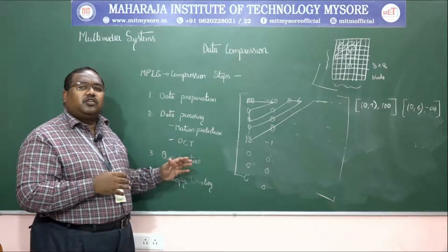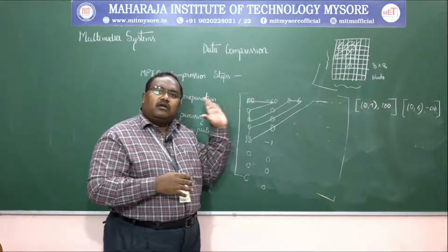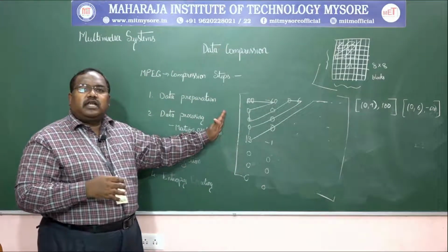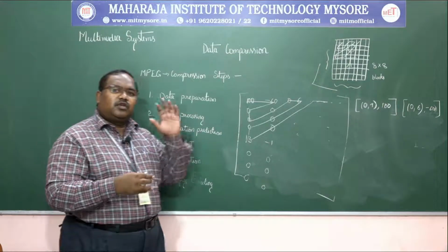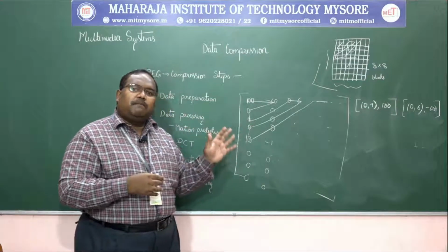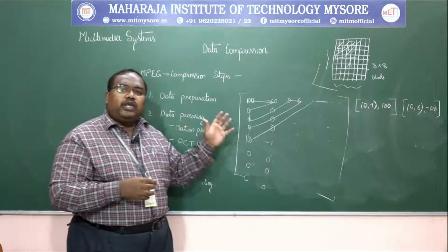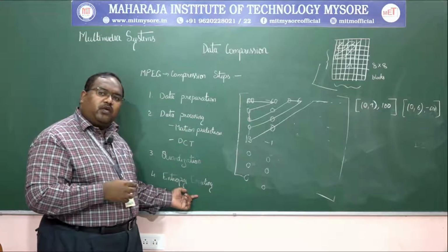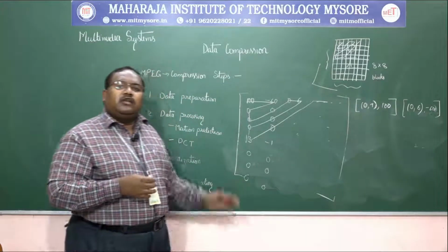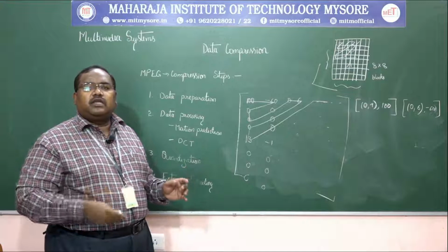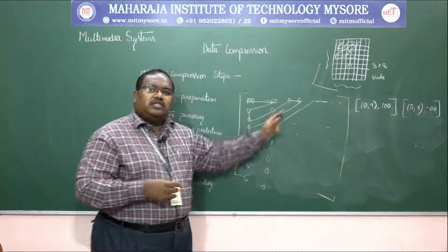When we have those DC components, we will be able to get a matrix or a macroblock like this, which is of dimension 2 cross 2. It is very difficult to apply algorithms on a two-dimensional matrix. In order to apply algorithms like run length and others, we convert the 2D into one dimension during the process of entropy encoding. To convert those 2D into 1D, we use the common convention of JPEG and MPEG, that is a zigzag motion of scanning.